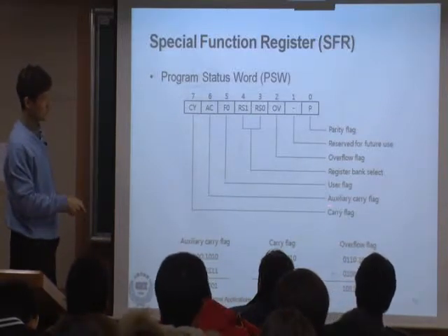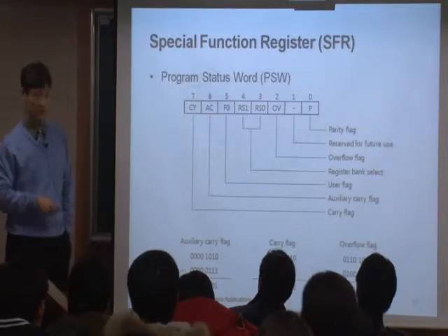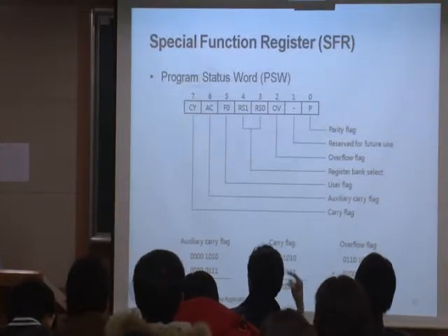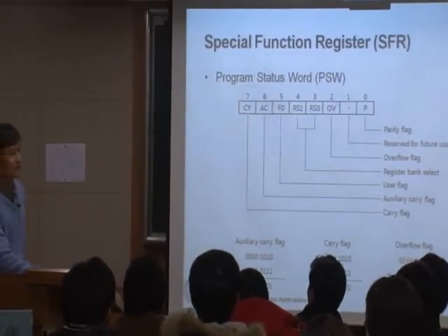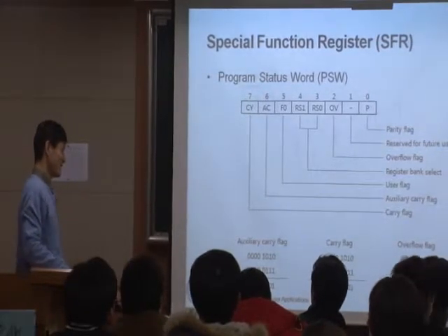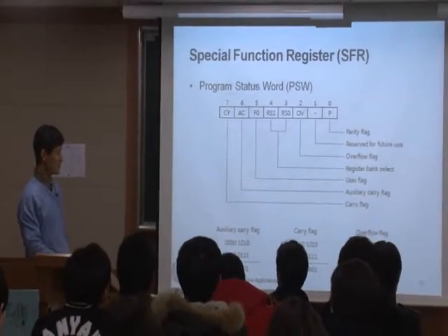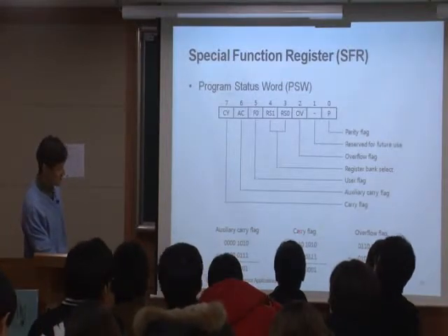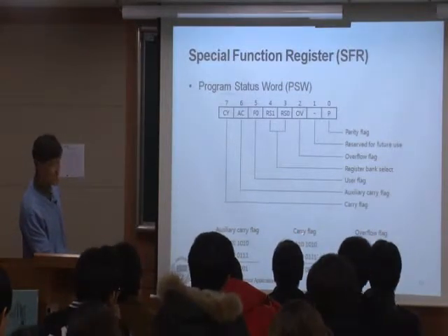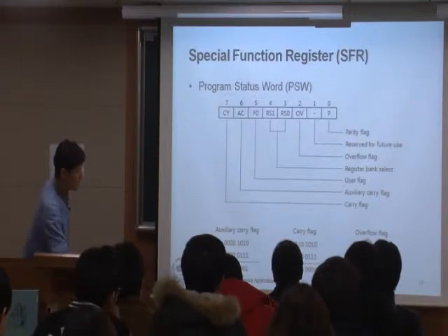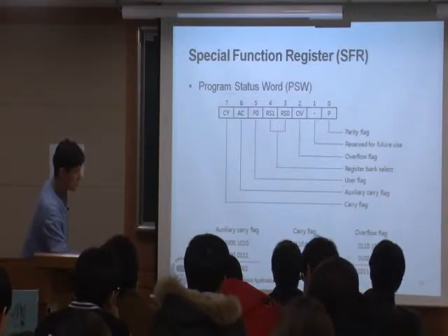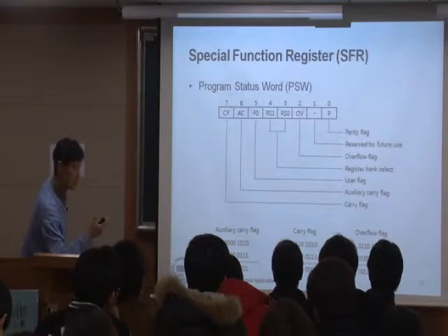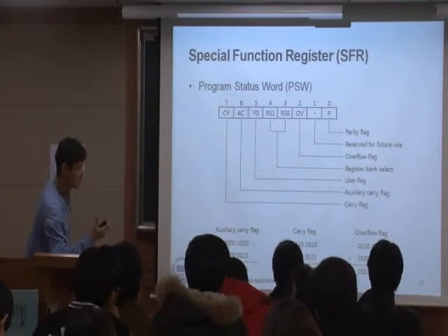First of all, what is carry? Let's see one by one. Carry. What is carry? 1 plus 1 goes 1, 1 plus 1 goes 1. Okay, that's exactly right. So look at here, 1 plus 1 goes 1. This is where the carry flag happens. So we have 2 different numbers, and each number is 8-bit, right? Because all of the other registers are 8-bit registers.